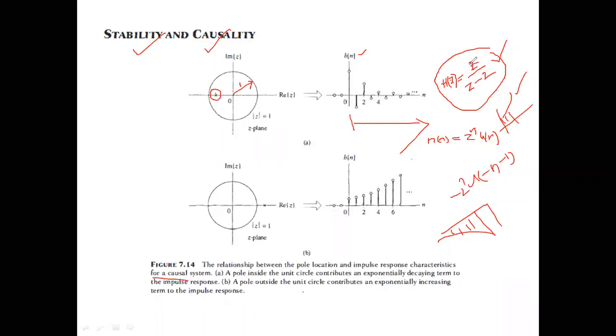Now z divided by z minus 2, if I equate the denominator to 0, I will get a pole at 2, right? You equate the denominator to 0, you get the pole. You equate the numerator to 0, you get a zero. Now see here, what is that property of ROC?